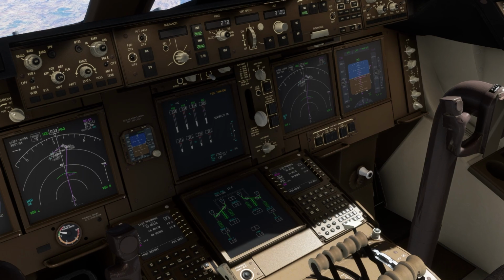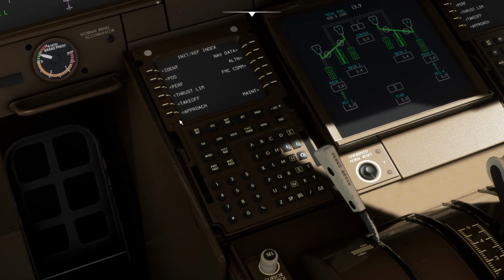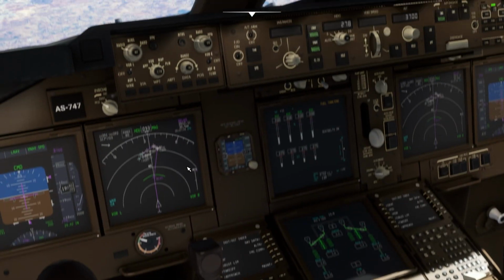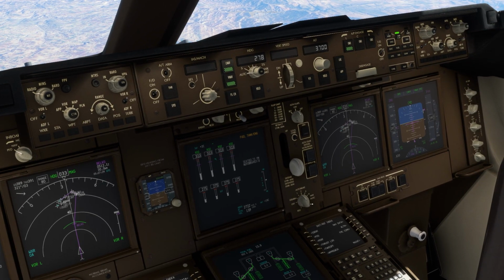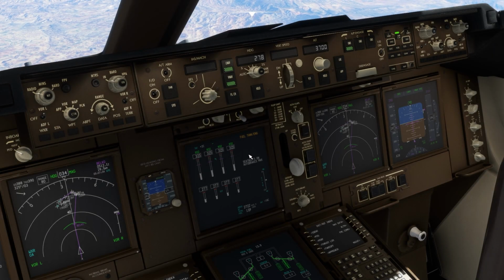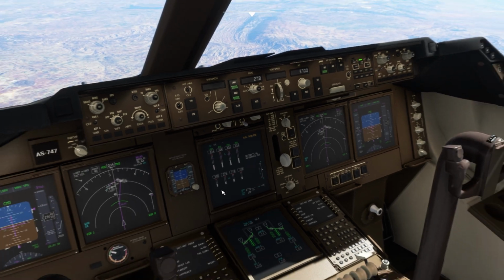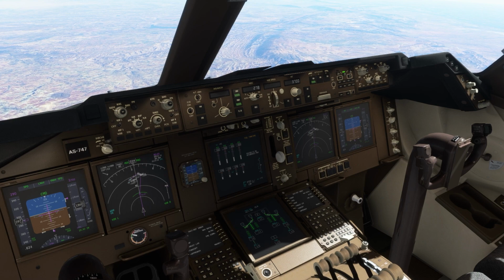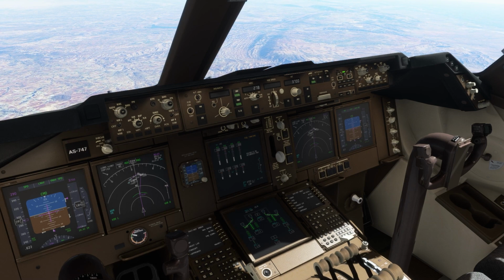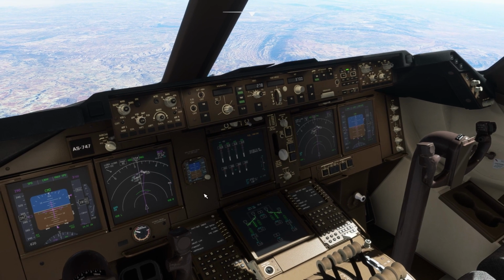But right now, as we don't have a landing performance calculator, the only information available to us is the approach. We can only set the speed and the flaps, and that's it. So you can just set the auto brakes to whatever you want. I usually land with the maximum brakes. You will see the auto brakes are now set to max. Once you land and the plane's speed is reduced, the brakes will be applied, and the plane will stop in a shorter distance, rather than eating up the whole runway, because you can overshoot the runway and that can be dangerous.